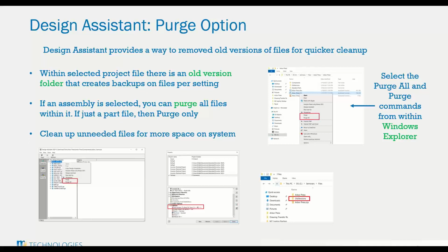-1 is all, or you can go up to 10. So the settings there are -1, 1, all the way to 10. To briefly explain, if I had a setting of 1 there, which it is, it only allows one old version of the file. So if I had a part file up and I hit save, it would record a version of it.